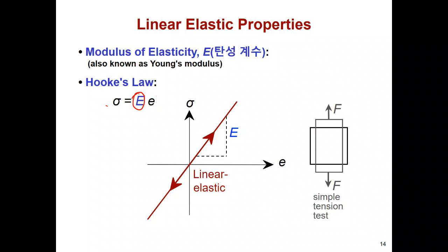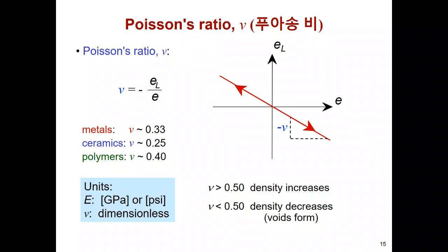The stress and strain relationship in elastic behavior is linear, and from the slope we can define the Young's modulus. This linear relationship, with one coefficient, the Young's modulus, is what we call Hooke's law. That's the basics of solid mechanical behavior.